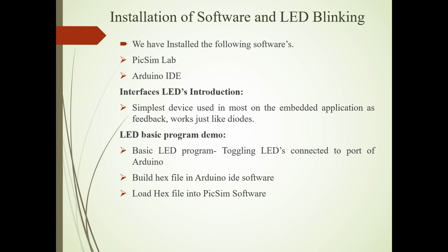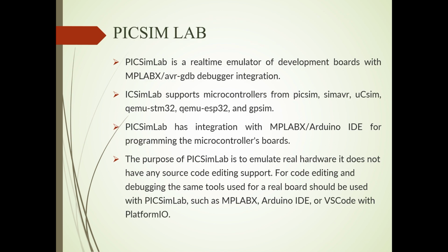Then we learn about the LED basic programming demo, in which we used a basic LED program, toggling LEDs connected to a port of Arduino, building a hex file in the Arduino IDE software. Then we load that hex file into our Proteus Lab software.